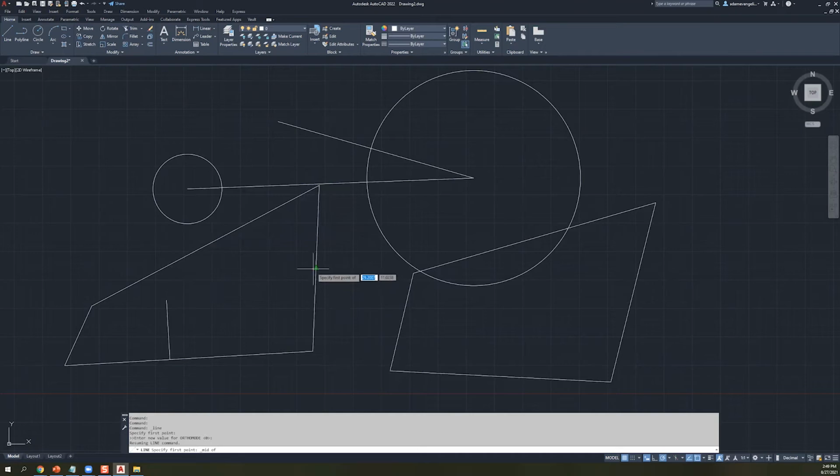And so this is a midpoint, this is a midpoint, and those are theoretically the two nearest ones that I could possibly click on. And what's interesting about snaps in general is that you don't have to be exactly on the snap position to use it, right? As long as it's highlighted like this, and I were to click, even though I'm off that point, it's still going to start over there, because that's the whole point of a snap, right? Just to put it on that point. So there's a bit of wiggle room that you have when you're placing and selecting those different features.